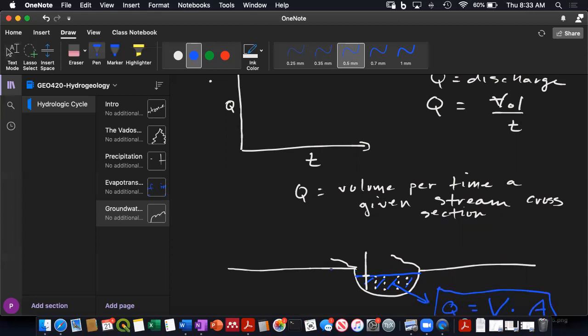We do that by measuring height, because that's easy to measure. And then we go back every month and we measure the discharge. And we create a relationship for this point that relates the height of the water to the discharge. And that's called a rating curve. There's lots of ways you do that, but fundamentally, we have to come out here every month or so and actually measure the discharge. And then what we monitor, because it's easy to do, is the height. And we just create a relationship between the two.